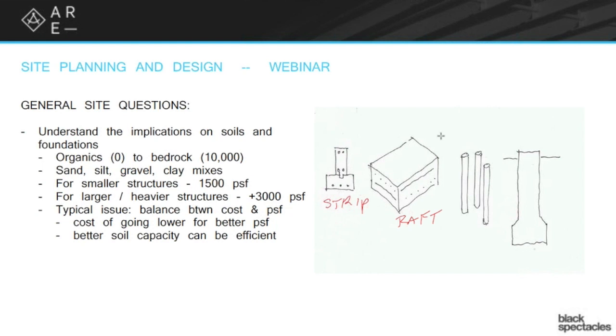Piles, you've probably all heard of, like wood piles, steel piles, and then caissons. One thing that they often like to talk about is the belling out of caissons in order to make the bottom wider. They have these cool augers that flip out as it's spinning down and going into the ground, so that when you get down to the bottom, they make the hole wider.